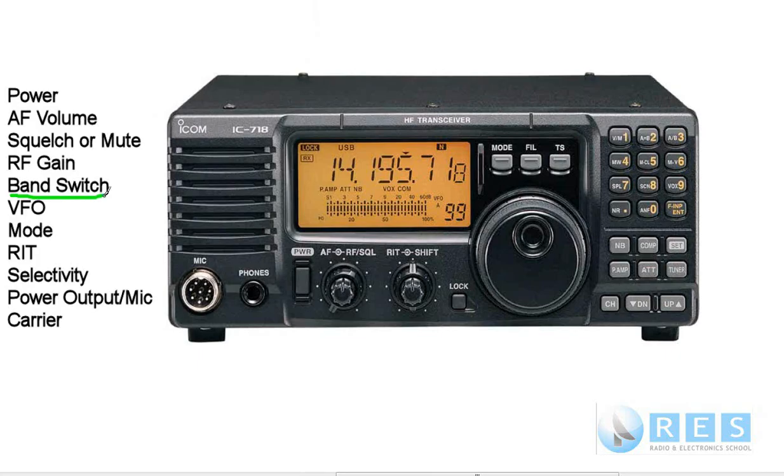The band switch. The band switch is how we change bands. We might want to operate on the 80 metre band, the 40 metre band, the 20 metre band, or the 10 metre band. Whatever. If the radio is capable of operating on that band, it will have a band switch to move between the various amateur radio bands. And on this radio, that's these two controls here.